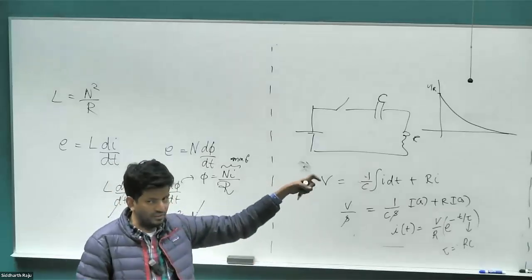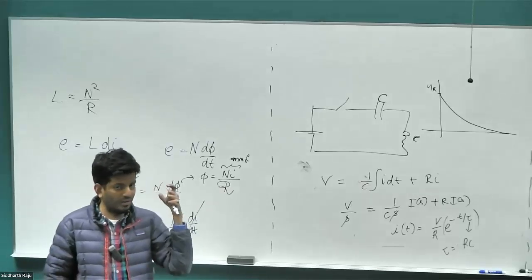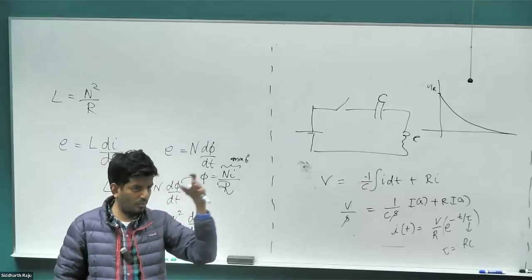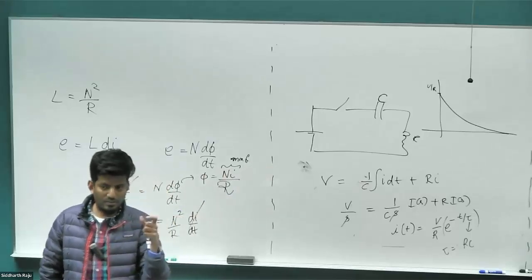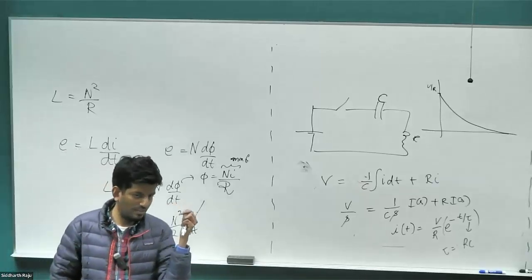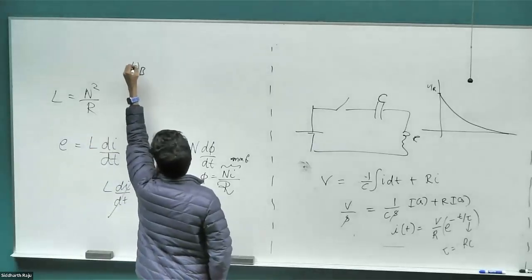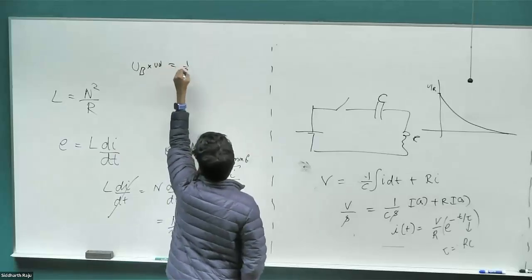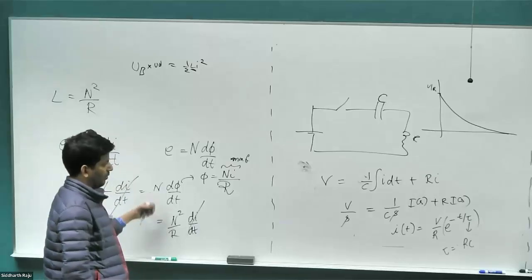You can go around and find the magnetic field in each of the air gaps. Right? Once we know the magnetic field, you can figure out the energy in the magnetic field: B squared divided by 2 mu naught times the volume over which it's spread out. And once you have energy, that is equal to, for an inductor, what's the formula? Half L i squared. So figure out the total energy, u times the volume, for each of those air gap sections, sum them up, that must be equal to half L i squared. And that L would be exactly the same as the one that you end up deriving.